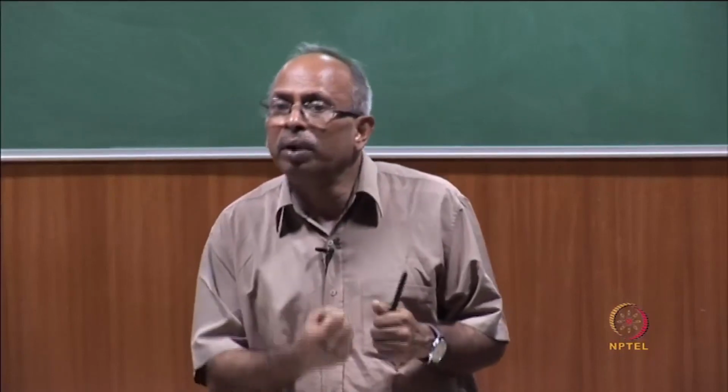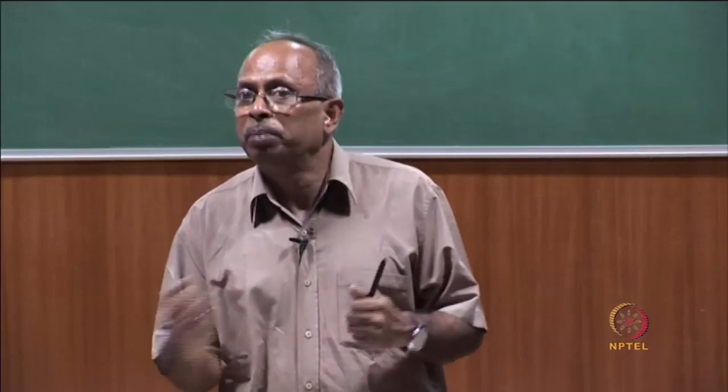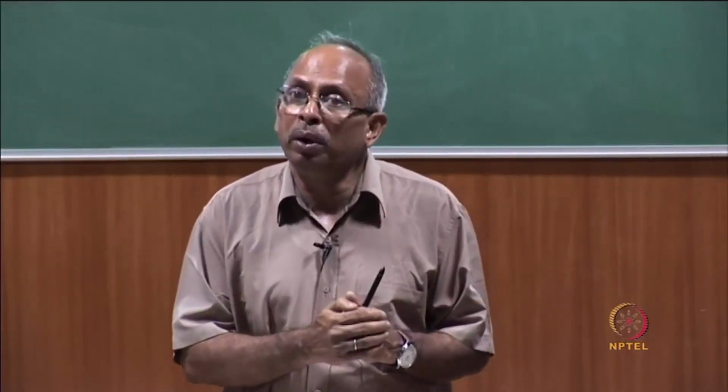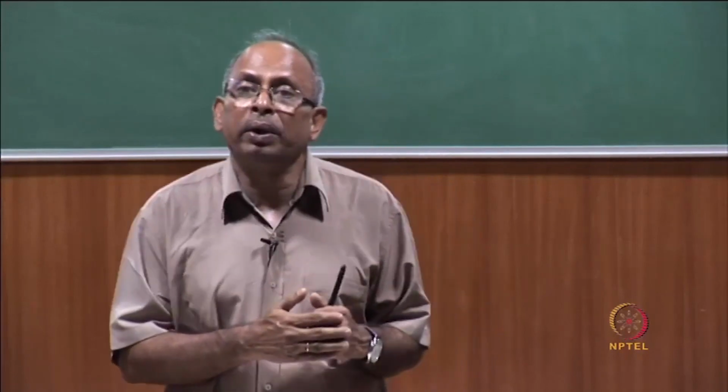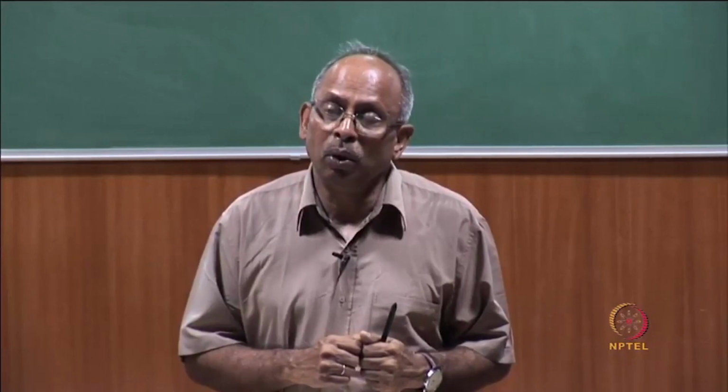So, movement of water from one gel place to another causes rupture of some of the bonds associated with the water, the van der Waals kind of bond that we talked of in the case of C-S-H gel.